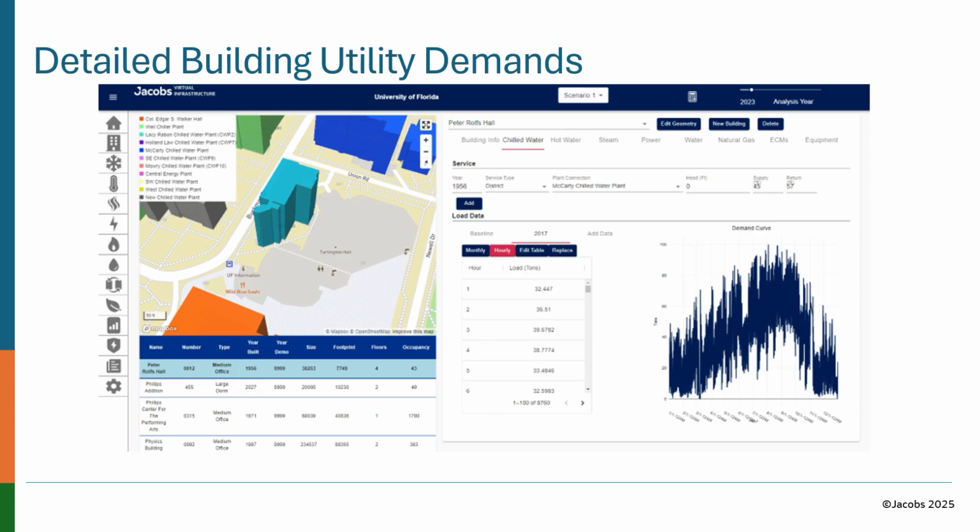Once you aggregate all those cooling and heating demands and put those out on one graph, what we like to do with our teams is plot out a given year and demonstrate where the opportunities are with those overlaid cooling and heating loads. We like to overlay a couple of other things too, like outdoor air temperature, wet bulb, dry bulb. That can come in handy when you're talking about hybridized systems. I think set points and setbacks are a good thing to demonstrate on these curves, and that can shine a light on a few areas where you can drive some efficiencies in your system design.